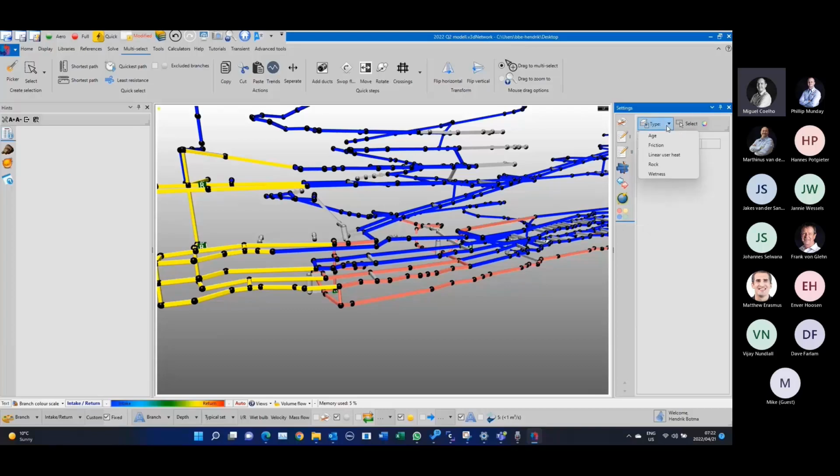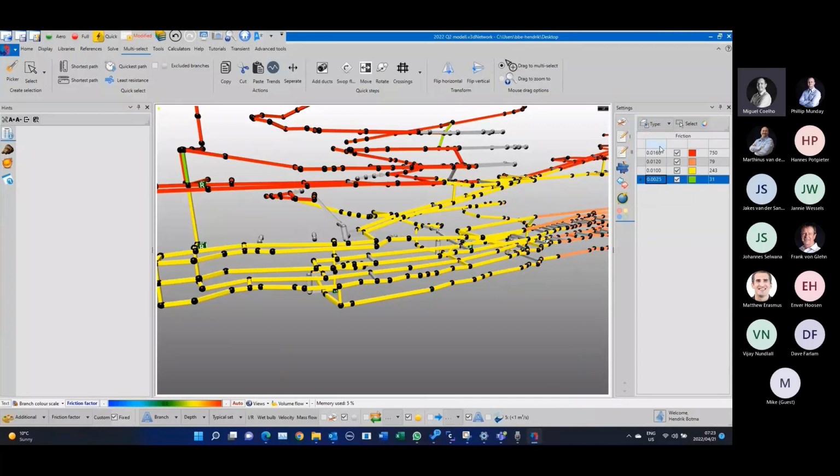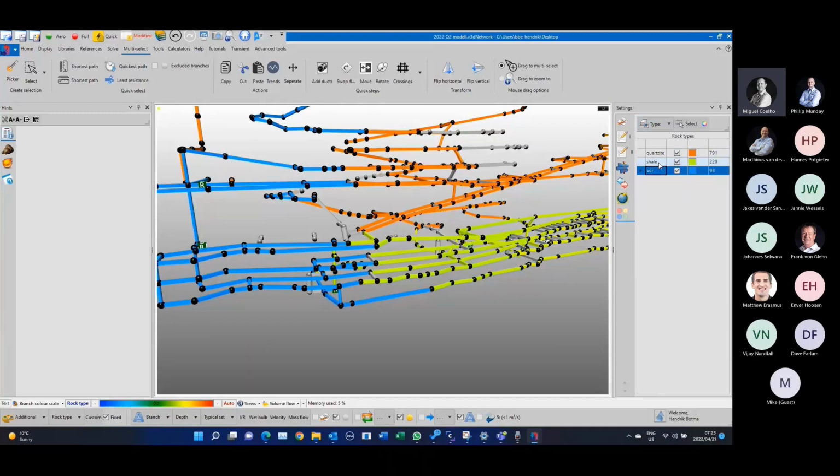Another new tab is the Variations option. This tab is great at identifying inconsistencies in a model, something that is bound to happen due to the size and complexity of modern ventilation models. Select an option from the drop-down to have both the view and the data column update.